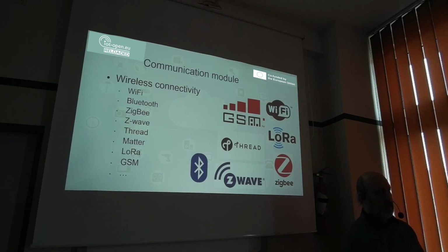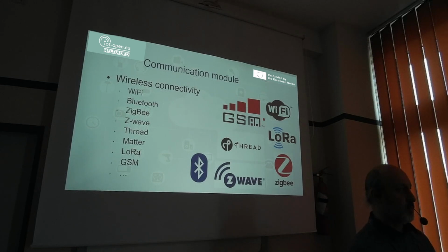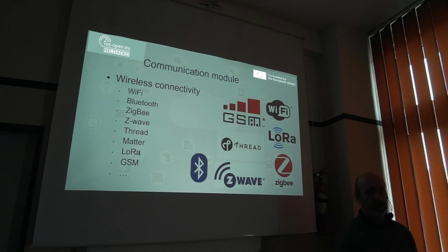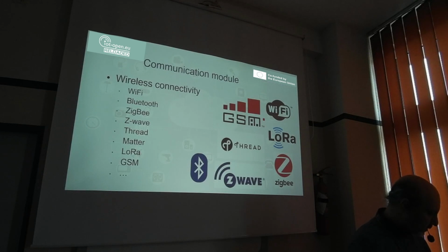But in IoT, because Wi-Fi is more power consuming, there are also other possibilities invented, like Bluetooth Low Energy, Zigbee, and additionally Z-Wave, Thread, Matter, and for longer communication, LoRa or GSM. So everything depends on the needs, on the range of transmission that we want to obtain, and of course on the availability of other technologies nearby.